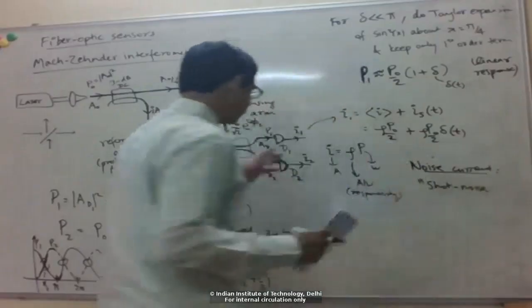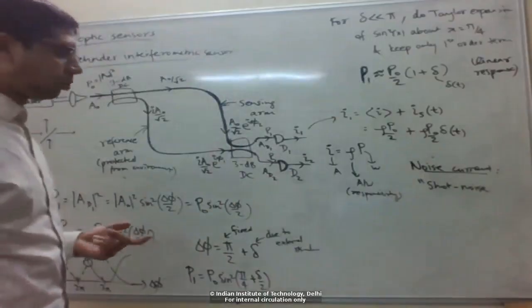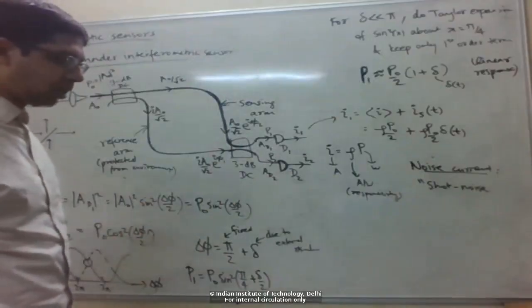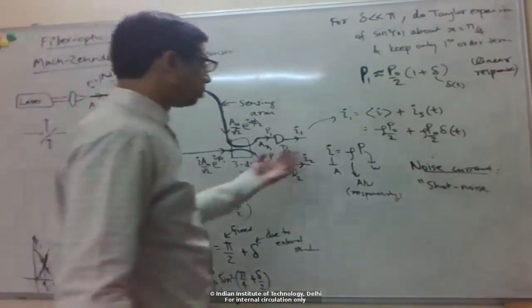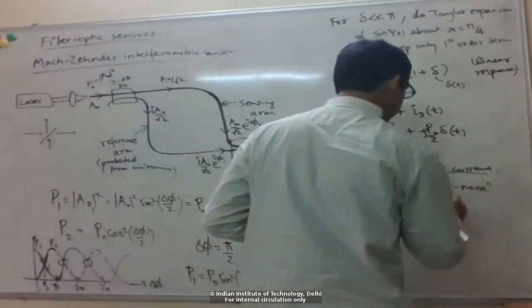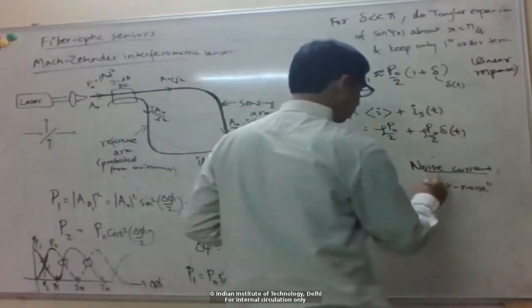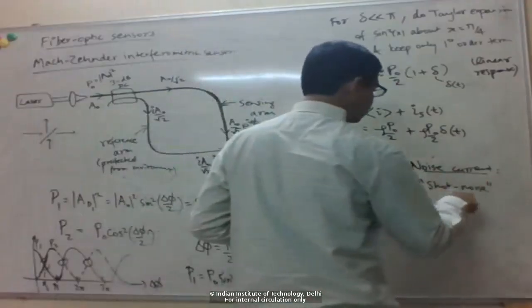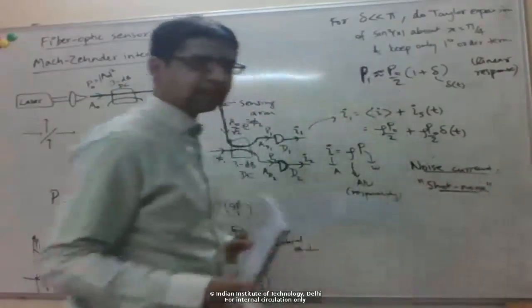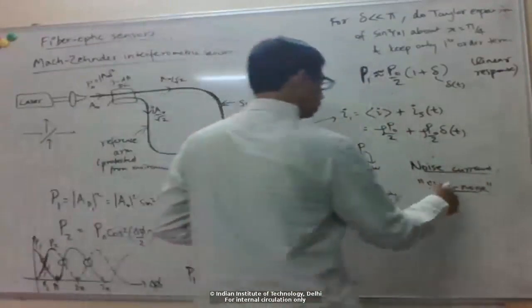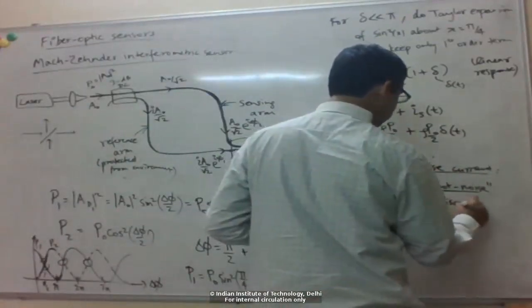Noise in photodetectors is another topic that we'll discuss in more detail in your optical communications course next semester, right? But for now, we just take the noise current to be a certain value. So if the detector is what is known as shot noise limited, okay, that's the best that a detector can be. Shot noise basically comes from the discrete nature of the electrons.